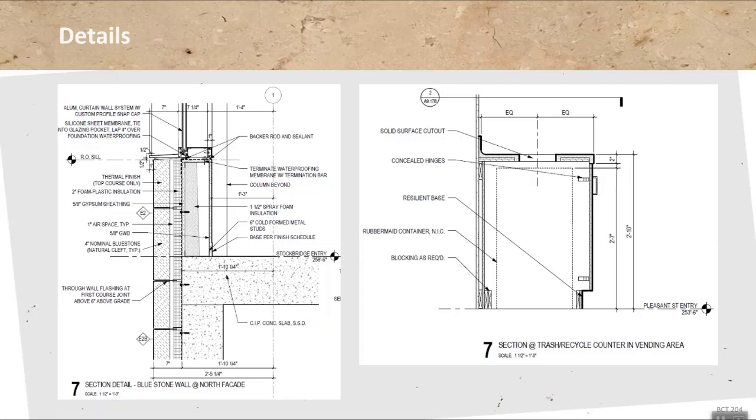On the left you'll see a vertical section. There's a floor plate, there's a wall, and you see the various things that you can see in the detail. So typically there's your level again, the floor level is called out so that you have a reference for what you're looking at. There might be other levels being called out. Then you're cutting through material, so this is where you're seeing boundaries of the various objects, material layers, and so on. And the materials are represented as hatch patterns, and we'll cover that in a second.